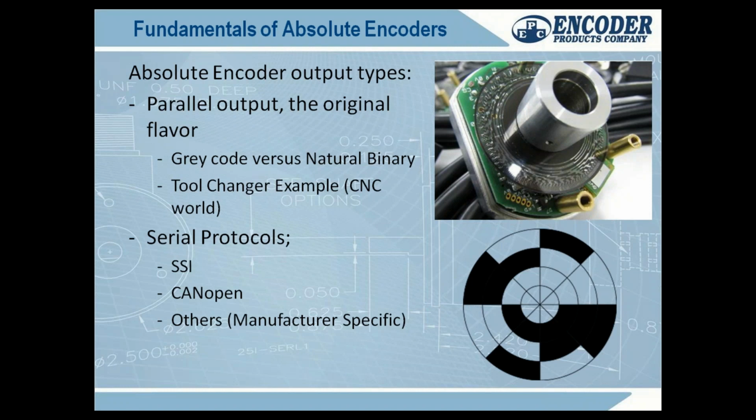That's a problem. So nowadays, you're going to get absolute encoders that put out bus protocols, and Ethernet protocols are there as well. That is to eliminate these gigantic bundled cables of having 1 conductor per bit. Now I can take 23 bits of single turn information, put it in a protocol, and still have a 4 or 8 wire encoder. Common protocols out there: SSI, CANopen, IO-Link, Modbus.